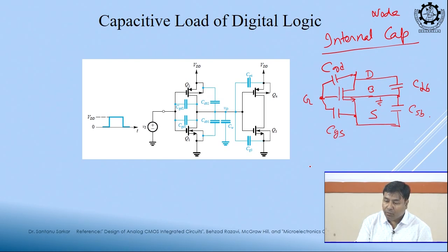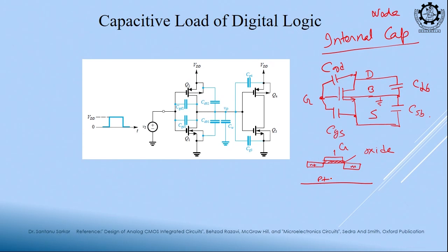and if you think why they exist, because we have a structure and they form a parasitic capacitance, right. This is our oxide and this is our gate. This is N plus diffusion and this is P plus substrate. So, we have the capacitances formed between two plates, something like that. Okay. So, these all are not real capacitance, these are called parasitic